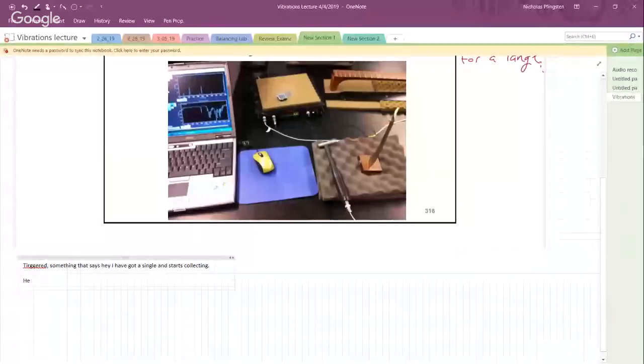The other thing that's important is we have to set up the input settings. I'll talk about what we did, but there's a bunch of different settings we have to set up. Averaging: how many averages we take. In fact, because my arm's not well calibrated, I like to take averages, to average out any noise that occurs, so we're looking at the best data.